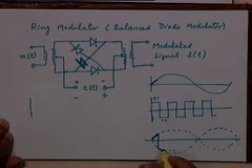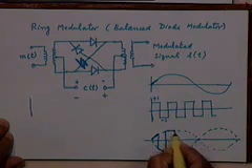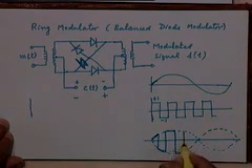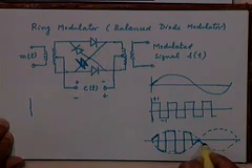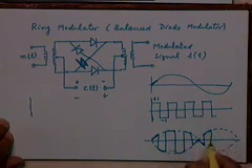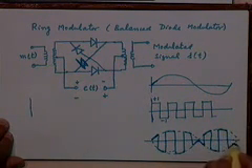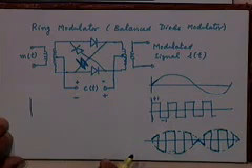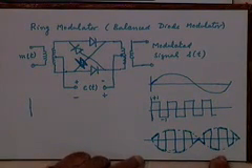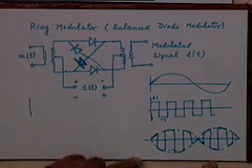The same message waveform appears with a negative sign, and so on and so forth, etc. So you get a modulated waveform which looks like this. Of course, once again the carrier here does not appear to be a sine wave, it appears to be a square wave, right.